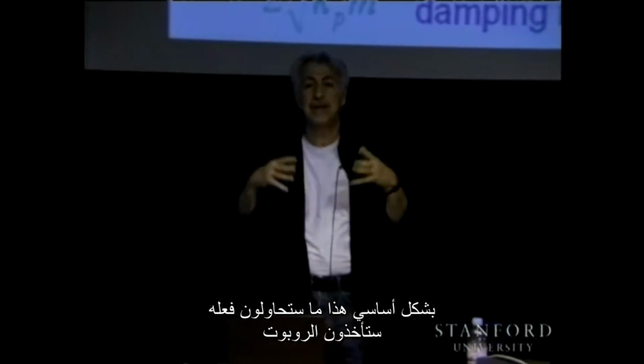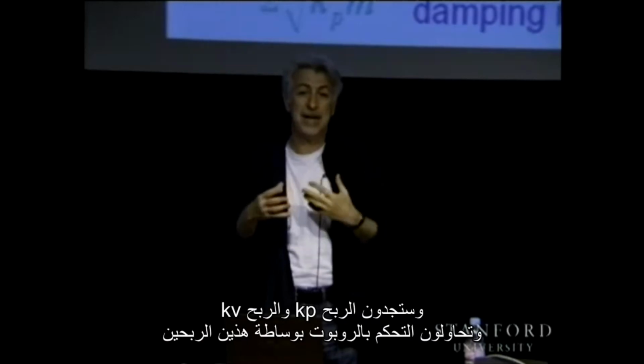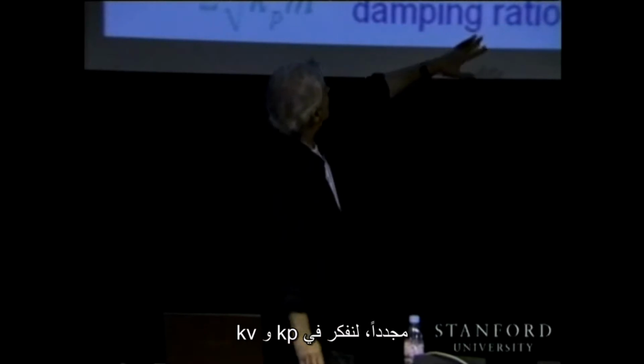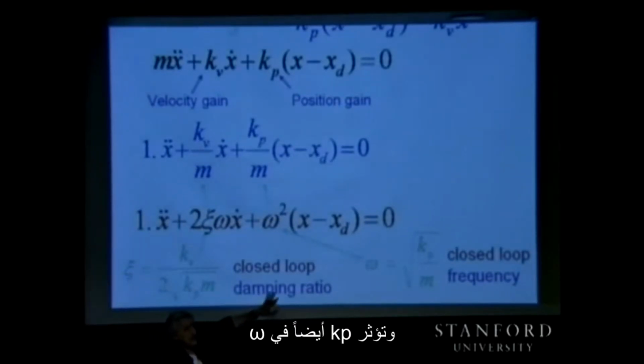You're going to take your robot, find those gains kp and kv and try to control the robot with those gains. So again, thinking about kp and kv, kv is affecting zeta, and kp is also affecting your omega.